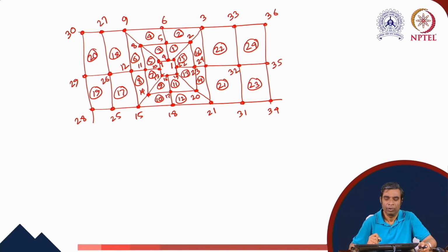When we finalize the mesh, we have to arrange the data in the IN array for blocks 1, 2, and 3 in such a manner that at the common interface of blocks, this is the left interface between blocks 1 and 2, and this is the right interface between blocks 2 and 3, the global nodes have the same coordinate corresponding to the different elements and the different local node numbers.